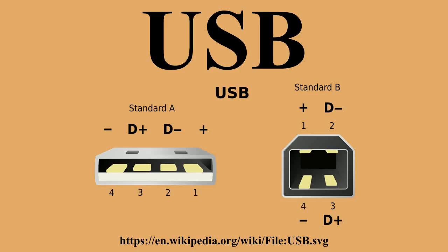USB devices are linked in series through hubs. One hub built into the host controller is the root hub. A physical USB device may consist of several logical sub-devices that are referred to as device functions. A single device may provide several functions, for example, a webcam with a built-in microphone. This kind of device is called a composite device.